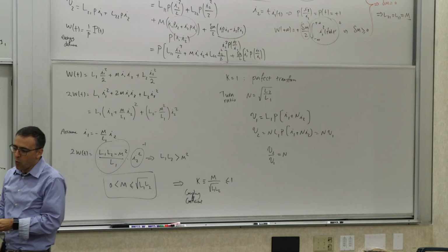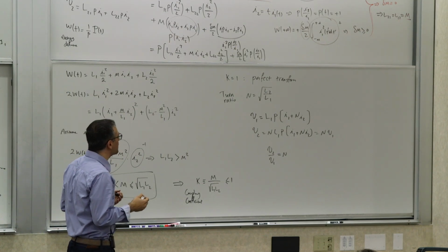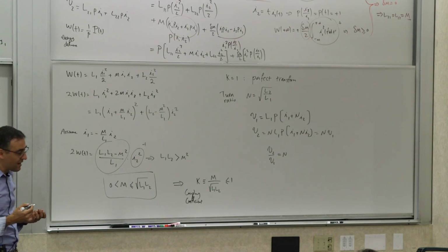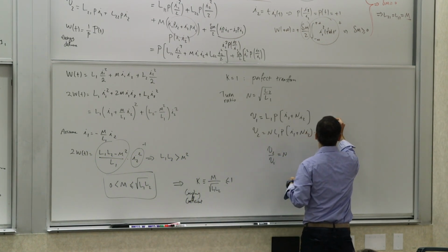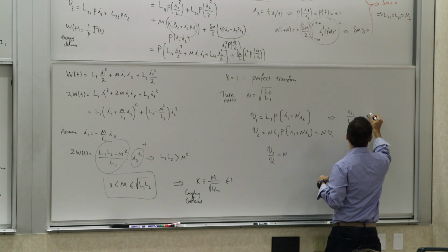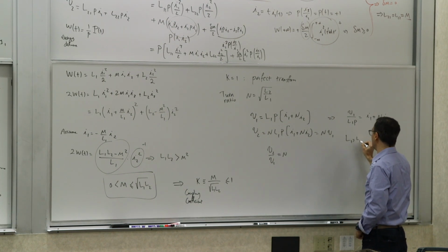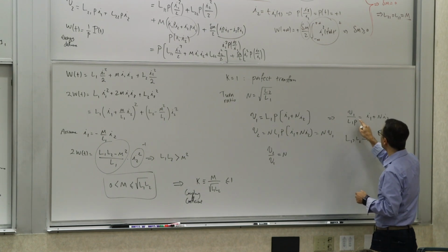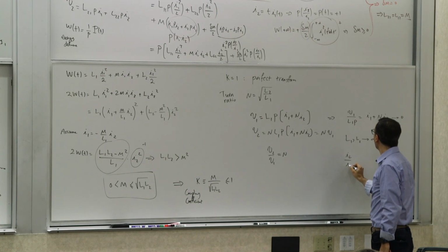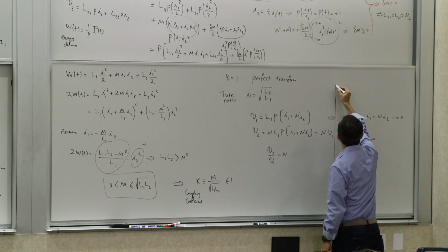Now, there's one more step you can take, which is called the ideal transformer. If L1 and L2 both go to infinity, if L1 and L2 are pretty large, what happens is that you can write L1p equals I1 plus nI2. And if you let L1, and therefore L2, because the turn ratio is finite, go to infinity, this goes to 0, which means that I2 over I1 becomes negative 1 over n. So this is what we call the ideal transformer.